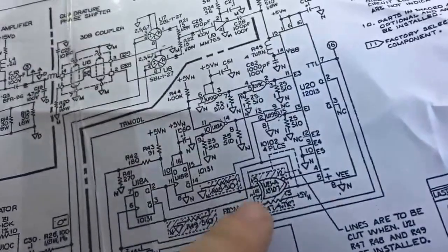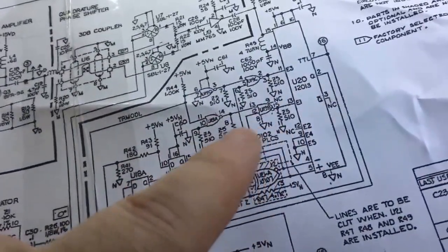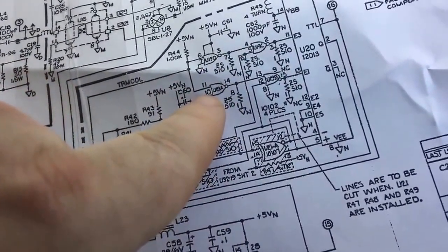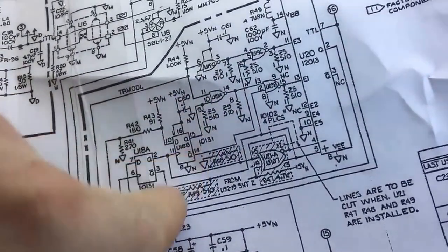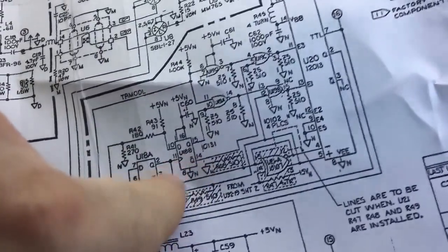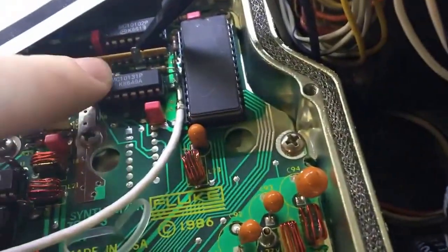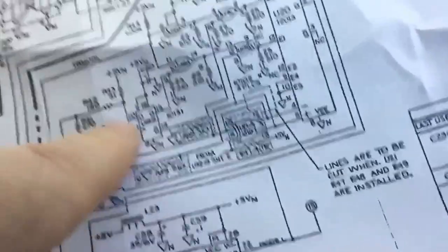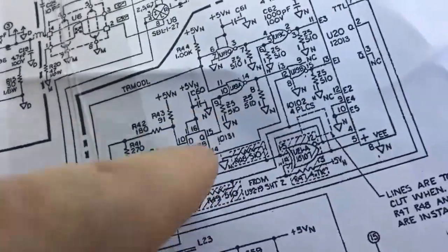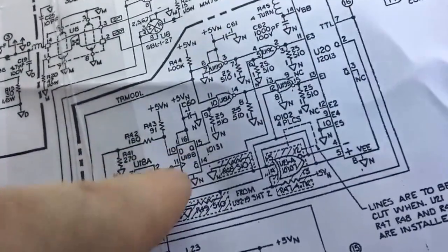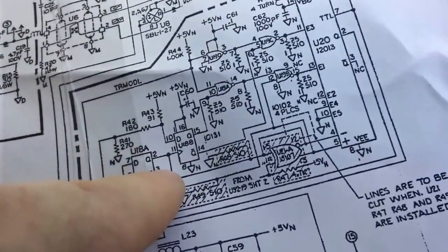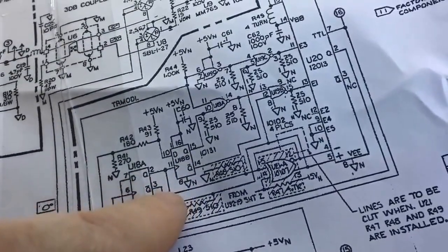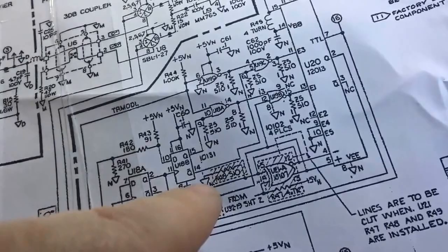Which brings me back to here. And part of that circuit is this U18, here we go, U18, right? Which is this one here, which I know is faulty. So it could just be that all that noise is from this particular chip and that will go away. But the fact that noise is increasing when it's errored versus when it's given a correct one, that's a good sign, because I've actually seen something which is different now.